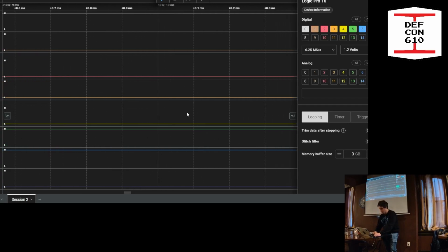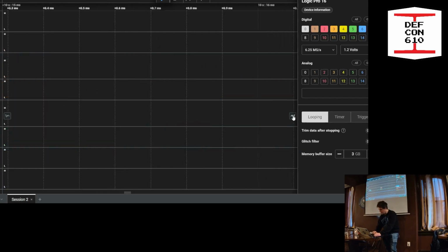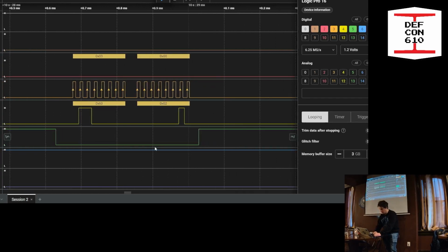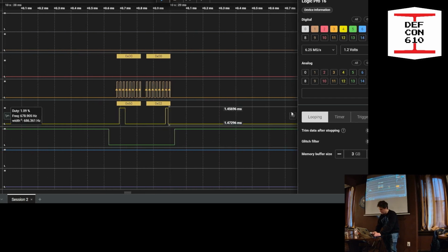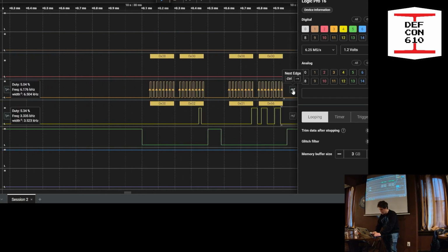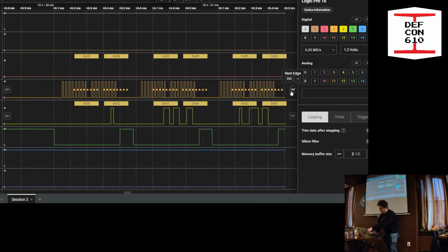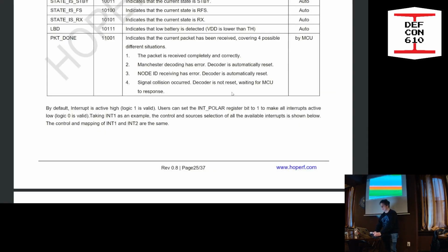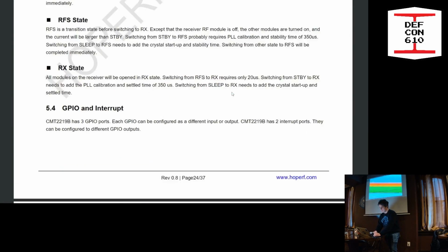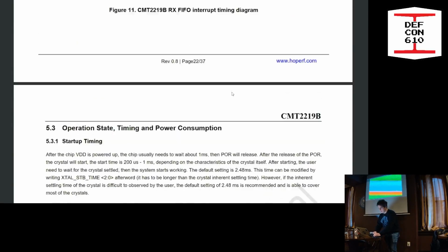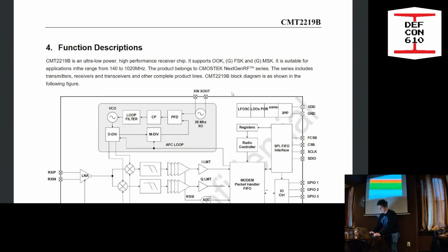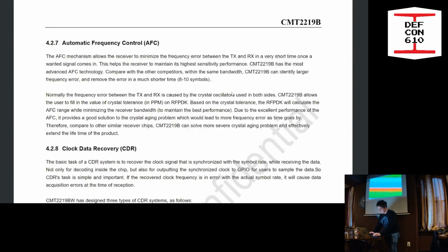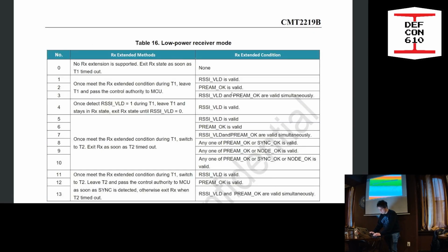You then see, if we go to the right, we then see 6C02 and more data in different regions, 0 and then 1, 2, 3, 4, 5. So that in general indicates I'm setting up different registers starting at register 0. If you go back to the datasheet, we have that big table of things to do.